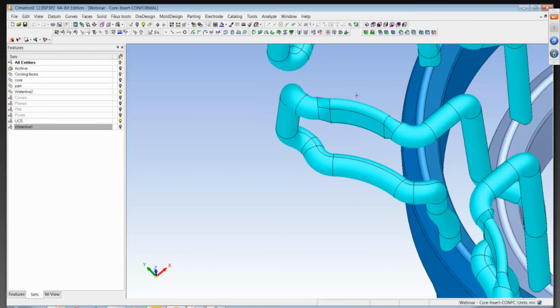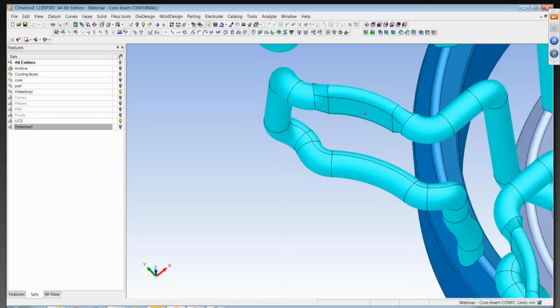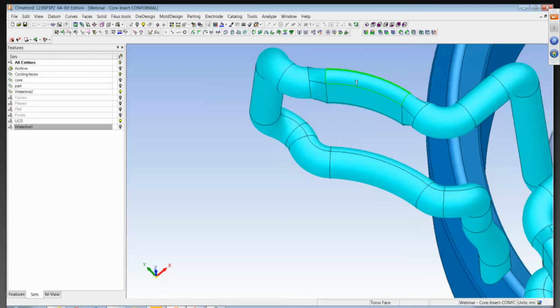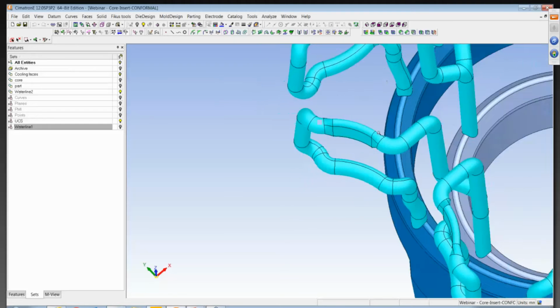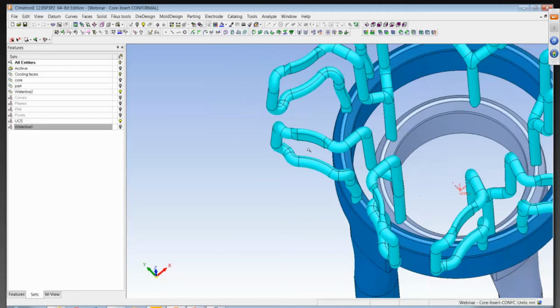But right here, in order to get between a couple of different mold features, it had to be narrowed. Well, with narrowing it, we also elongated it. The idea, again, is keeping that constant cross-section. Along the way, too, you see these transitions. It's nice to keep it nice and smooth, tangent to tangent transition if possible. The most important thing about this isn't so much perfect tangency, but that we're avoiding sharp corners. We don't want to have sharp corners anywhere because we want to avoid cracking in the core.